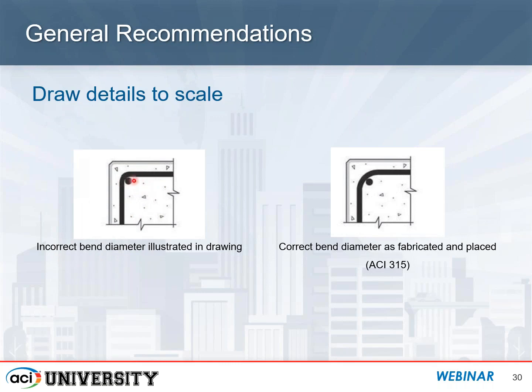It shows where the longitudinal bar is with respect to that incorrect bend diameter, whereas on the right, this shows the correct bend diameter on the drawing with the longitudinal bar at its correct location, and you can see there's certainly a difference between the two. So, again, especially in cases where you're anticipating congestion, having details like this will help in the long run.